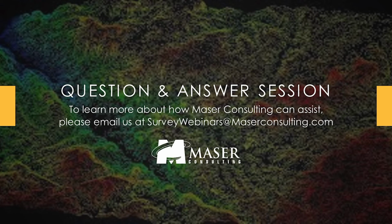That's a good question. So it really depends on the site. Anytime we're going to be doing planimetric extraction, where there's a lot of buildings, roads, stuff like that we're going to have to map, I like to also collect simultaneous photo data, because anybody who's worked with LiDAR data, once you get into it, it's just a bunch of white points, and it's hard to tell the difference between edge of pavement and the shoulder of the road, things of that nature, without the photo-based data.